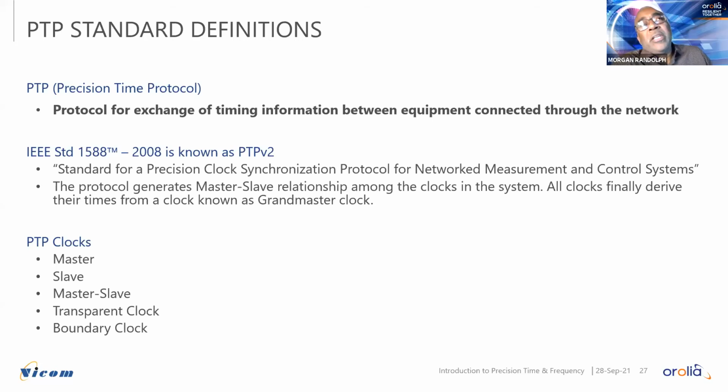Yeah, so in the case of our device, GPS is going to be more accurate because it's coming right off of the satellites, okay? But we have IRIG cards within our device. So when you take that Stratum 1 device that's connected to GPS and you have an IRIG card in there and you provide IRIG to another device, that's where those times come into play.